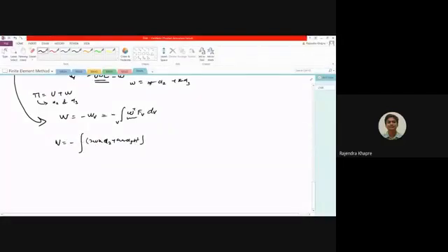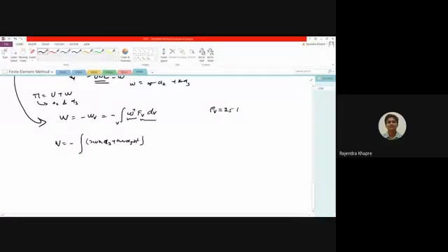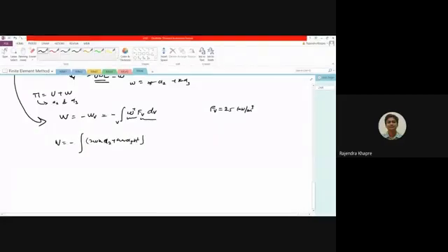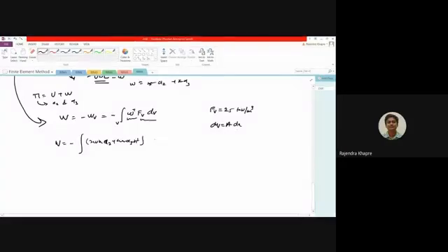So this is what I am writing randomly over here, and here this FV into dV will be slightly changed. Okay, so this is force over the volume. This is nothing but, say, if you take a density of concrete, this will be 25 kilonewtons per meter cube. Okay, and your dV is nothing but your area into dx. So all we have to do is just write the value of FV over here as 25.